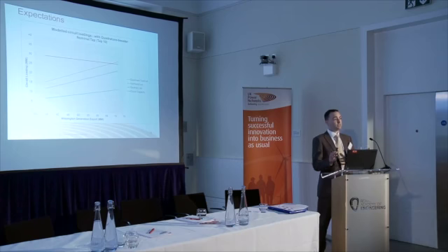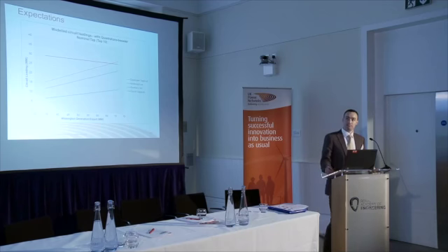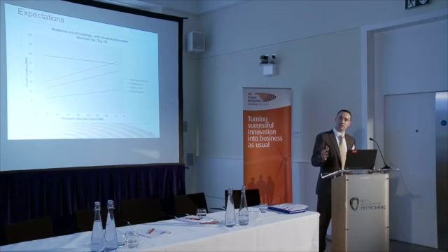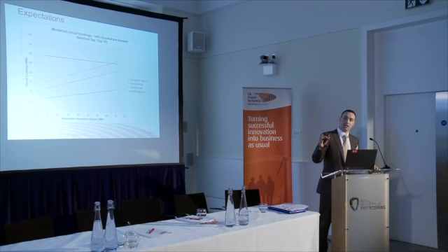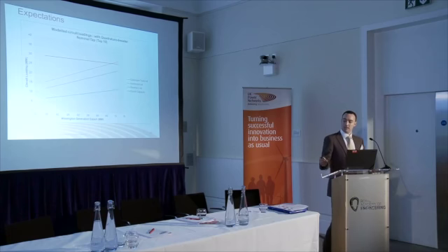That's one of the reasons for putting it into the Downham circuit as opposed to the Norfolk. If we'd put it into the Norfolk, whilst in theory it would have worked because we could have boosted the power in that circuit, we would have put an impedance in there which would have made the problem worse at nominal tap. So what you can see from this graph is that the power flows through the Downham Market circuit and the Norfolk circuit are more closely aligned, and that we can get around 10 megawatts additional capacity without the need to change the phase angle at all.